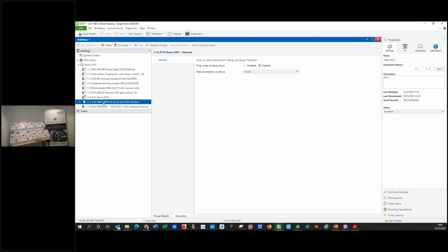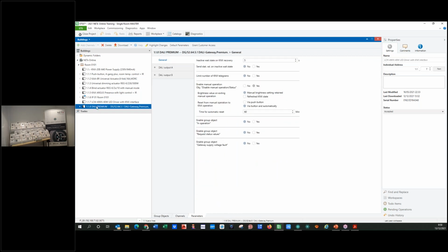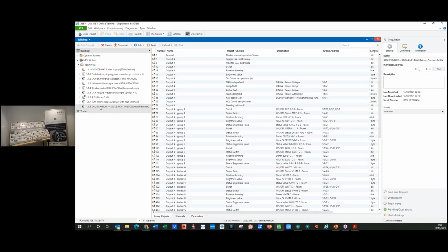Okay, a second dimmer, because we have 2 dimming lights, one in the front and one in the specific spotlight in the top of the practical boards, and a DALI gateway. Okay, in this case is from ABB, a DALI gateway that is not physically present in the installation. We don't have 8 DALI gateways in this small, because these practical boards are for my basic trainings, and in the advanced boards there is no space for them. We have it in the design of my project, but it's not present in